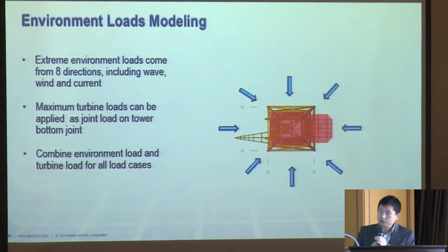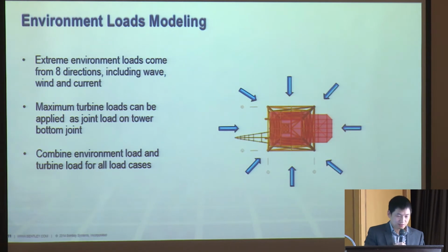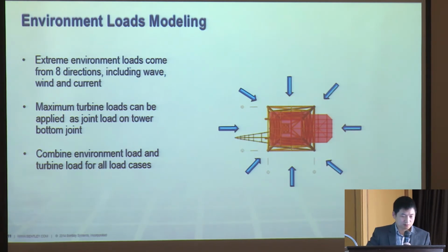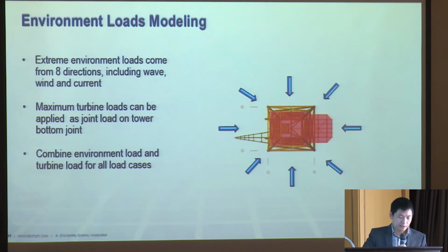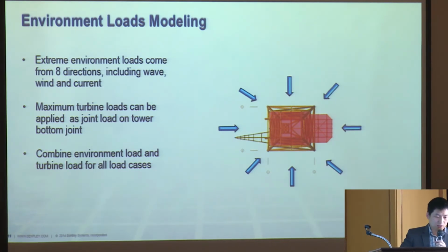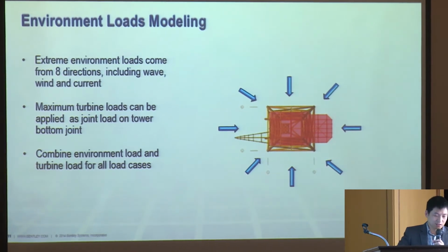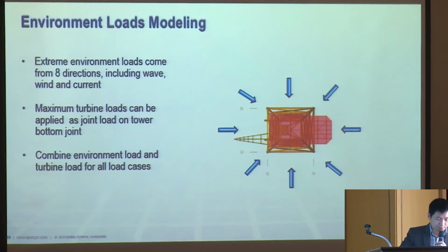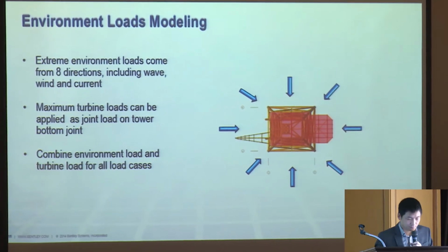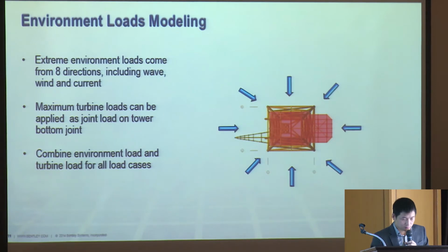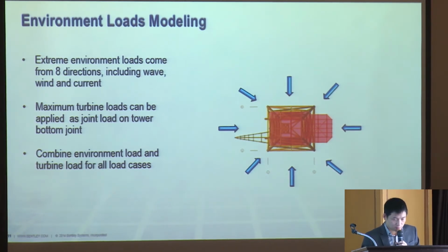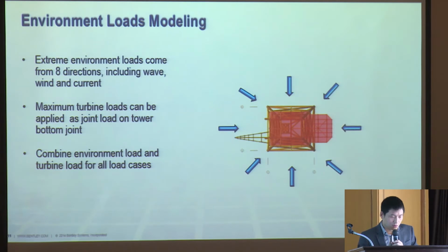Here is the SACS load modeling capacity. Usually, you can model the environment loads from different directions, including wave, wind, and current. And here we support 5 different wave theories, and we can calculate the apparent wave period.